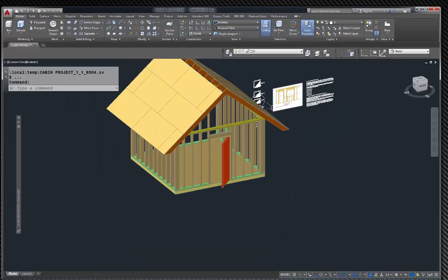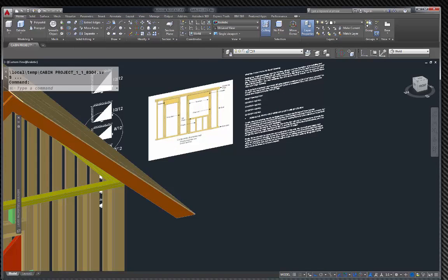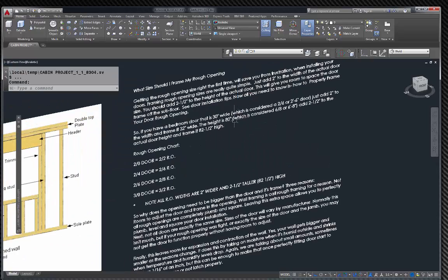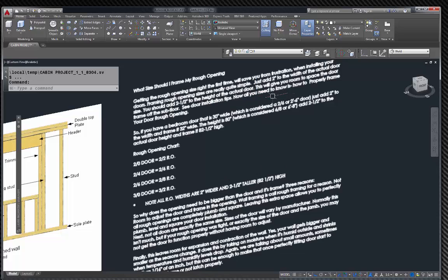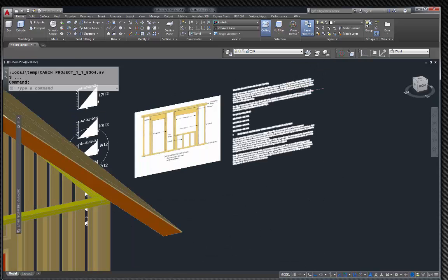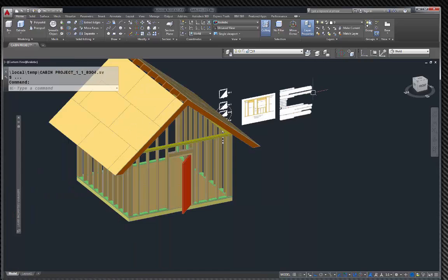Okay, we went through our door stuff, and if you remember, we talked about spacing around the doors, that we wanted 2 inch on the width and 2.5 in the height. Well, for windows, we want 2.5 on both height and width, okay? So if your window is going to be,